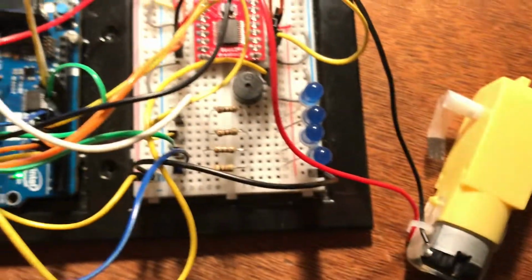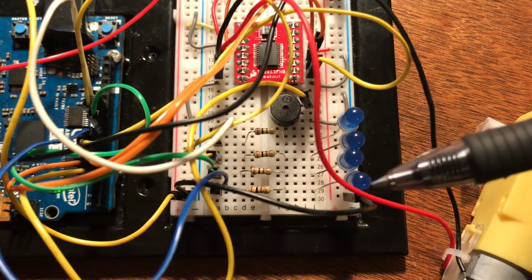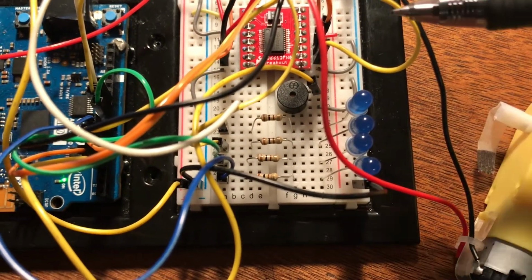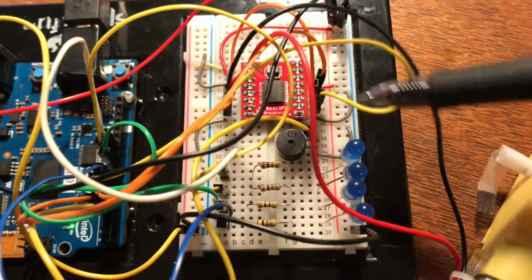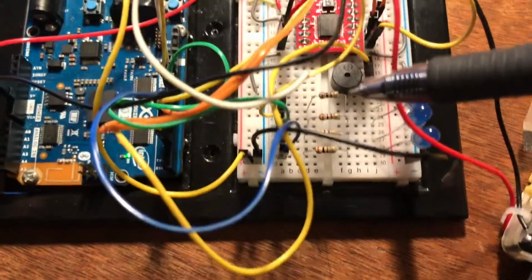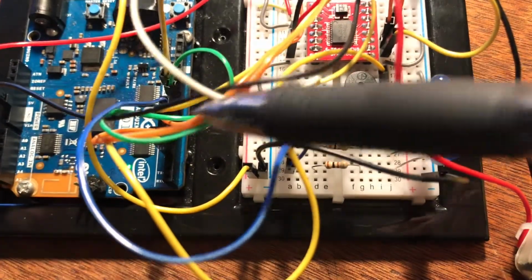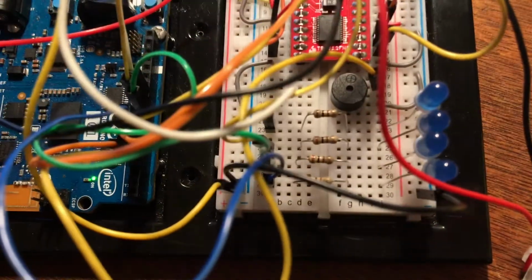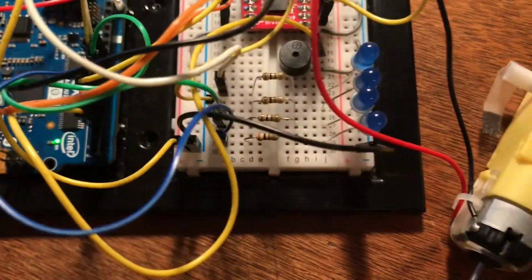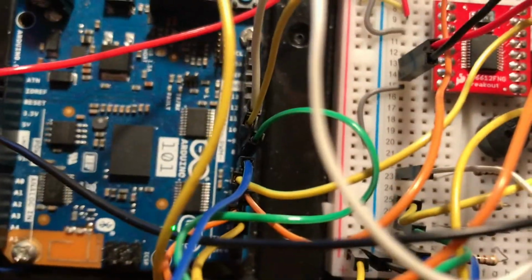We then also have 4 LEDs set up, LED 1, 2, 3, and 4. All of them are grounded by their cathodes connecting into this negative column and grounded by this black wire. They all also have a 100 ohm resistor that they connect through to their pins. This first LED is connected by this white wire to pin number 10.